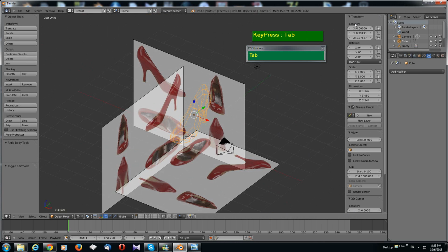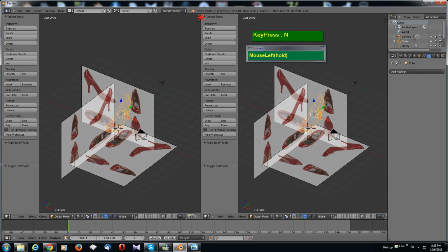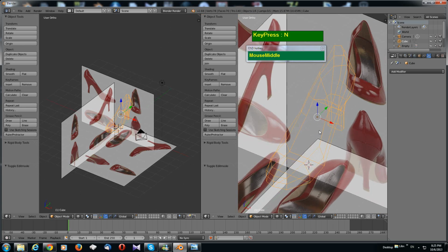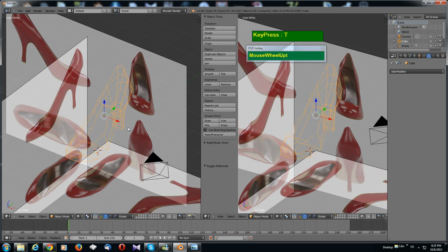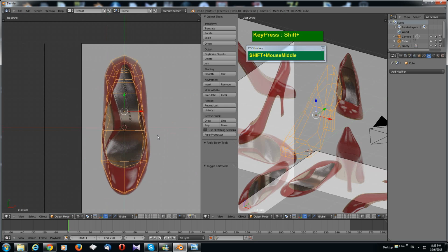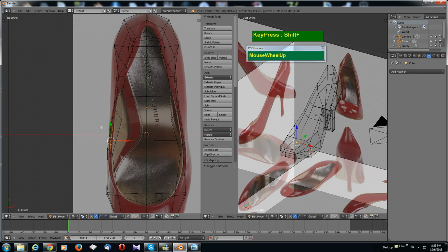Okay, I'm going to close the properties window here. I'm going to split another window. So open up a 3D view, and then go to the top view here. Then go to edit mode. So when you click and select, you can see in the 3D perspective view which vertex is being selected.